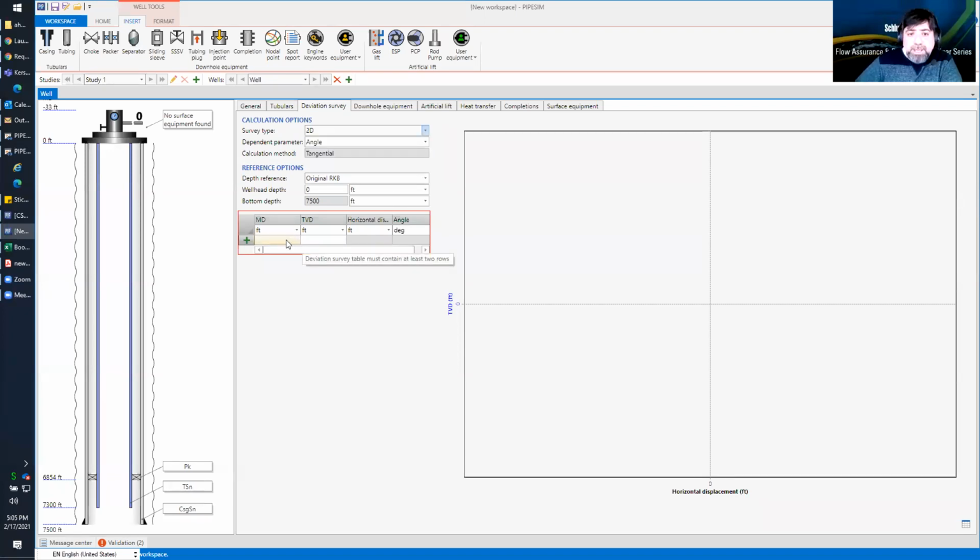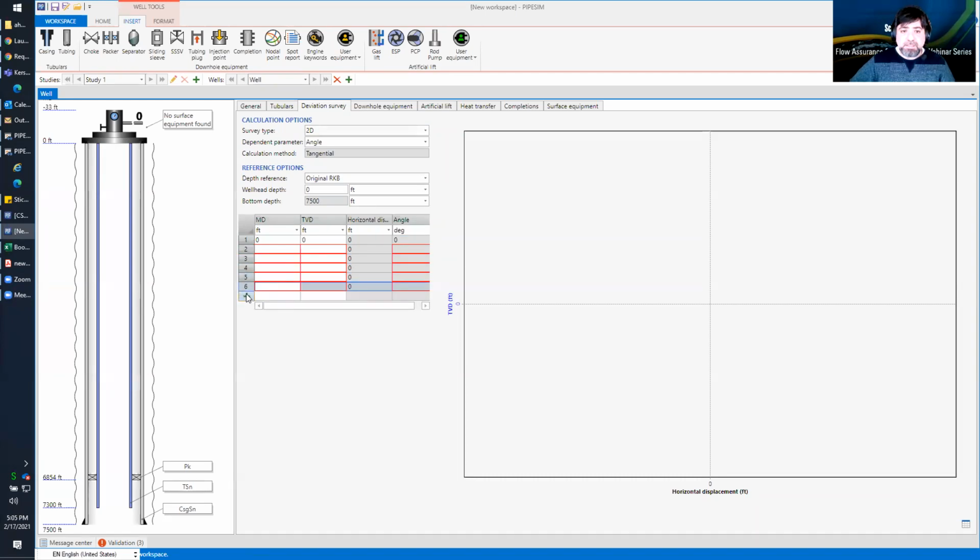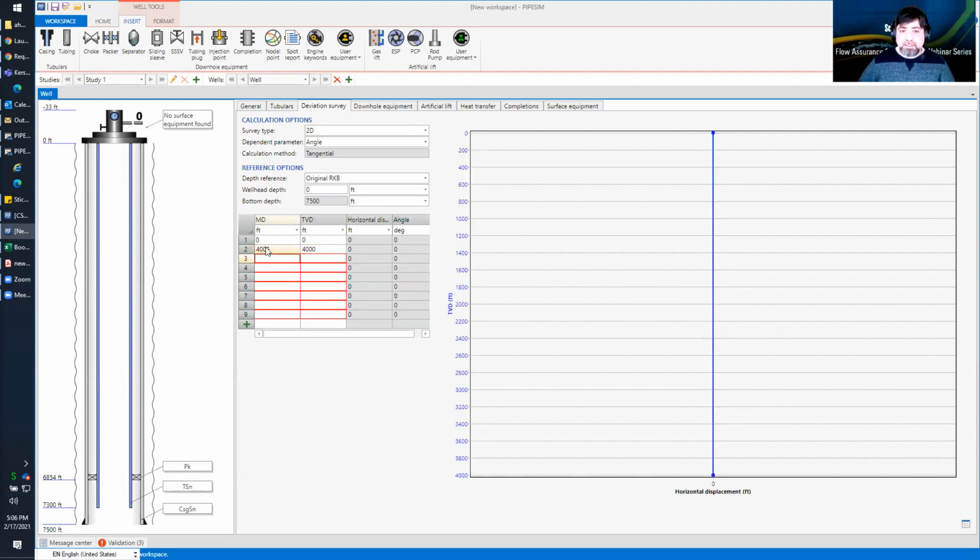So I'm going to add a deviation survey, starting at 0, 0. Then I'm going to add, let's say, maybe 7 or 8 points. From 0 until, let's say, 4,000, it is vertical. So 4,000, 4,000. And now I start to deviate. You'll notice that while I'm adding these points, the curve will be updated. And usually the MD must be equal to or more than the true vertical depth, because if we are deviating, then the length will be more than the true vertical depth.